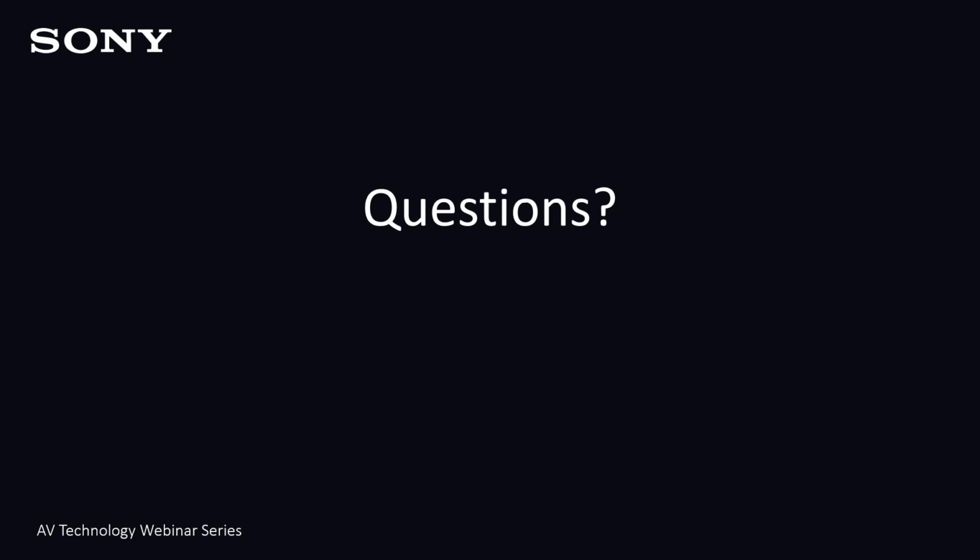We've got a question from Saeed. Does it support Microsoft Teams and any other applications? Let me try to answer that one, John. To fully integrate with Microsoft Teams, you would need to convert the HDMI output to USB 3 to go into the local laptop. Or, and I have not tried this, so I can't answer directly, if Teams would let you take a video stream from an RTSP source, then that should work too.